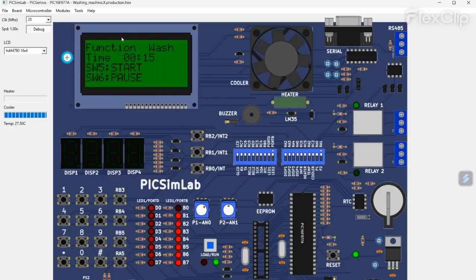To demo the door status, in the code we have written a particular button for interfacing the door, which is switch 1, which is RB0. Now I am long pressing RB0, which is switch 1, indicating the door is open, close the door. If I remove the long pressing of switch 1, it represents the door is closed, and the program will resume.